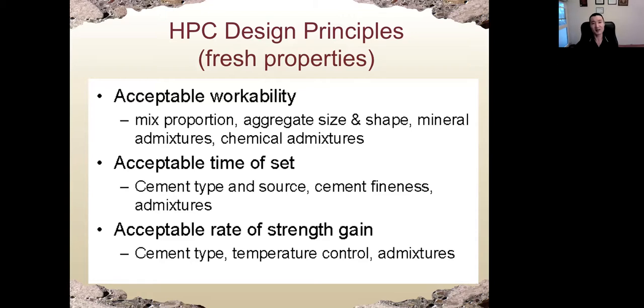The last part, let's talk about the basic design principles for high performance concrete. First of all, the workability should be good enough. Based on mixed proportions, we can change, for example, water cement ratio. We can change size and gradation of aggregate. We can use mineral admixtures, sometimes chemical admixtures to achieve desirable workability.